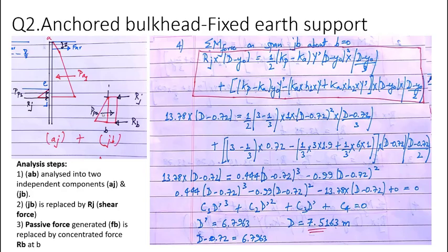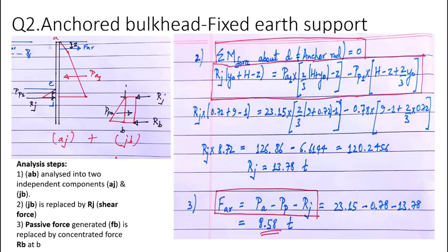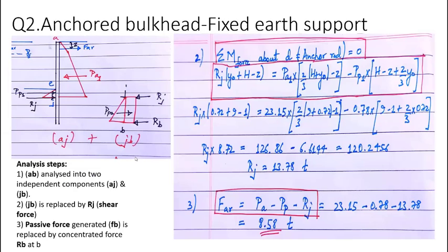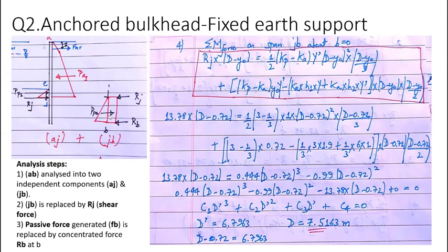As we can see earlier, it is the effective passive minus active, as shown in this figure. Active pressure is also acting, passive is also acting. So one is for the triangular pattern and the second is for the rectangular pattern. It comes out to be half Kp minus Ka gamma submerged, because it is below the water table, times D minus Y0. This is multiplied by the lever arm, the centroid at one third of this height, so D minus Y0 by 3.